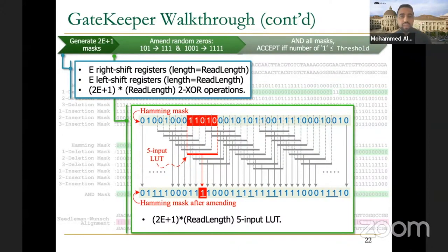And these lookup tables normally have a fixed size, meaning how many inputs you have to the lookup table. In today's FPGAs, it's around 6 to 7. In old FPGAs, about 2 to 3 inputs. So you cannot apply any function within a single slice that has more than 3 inputs, for example. So you need to use multiple slices or multiple lookup tables.